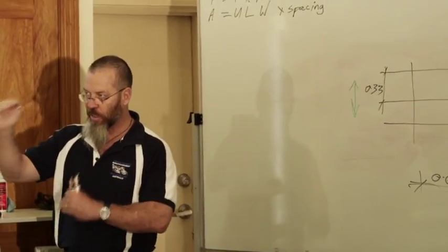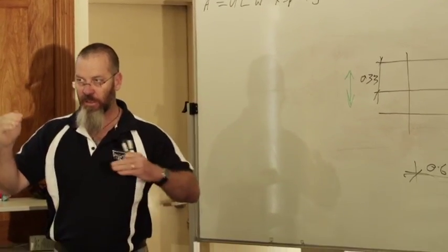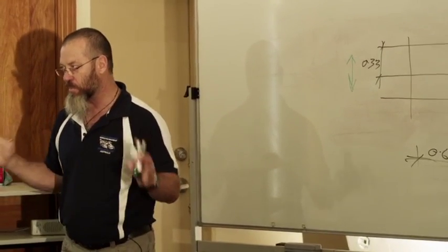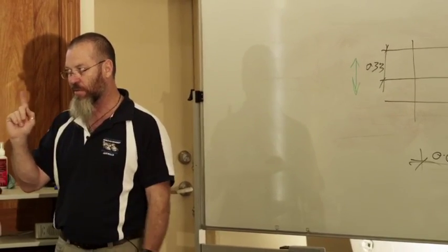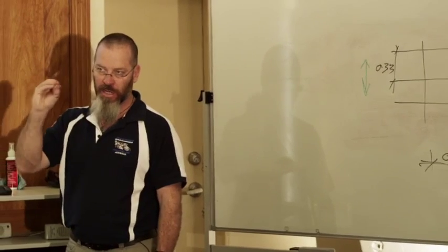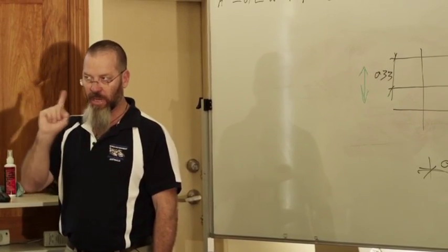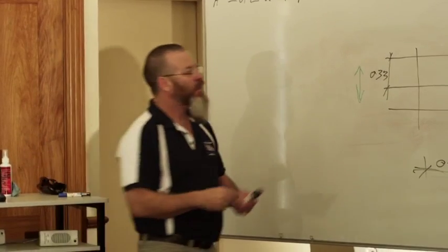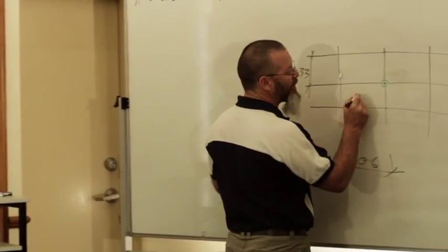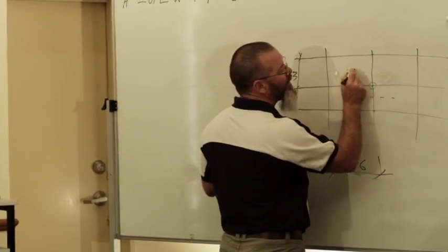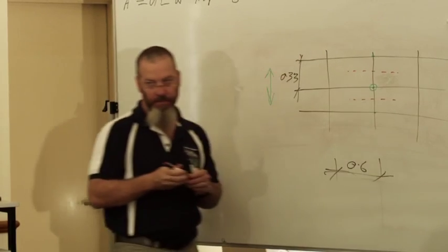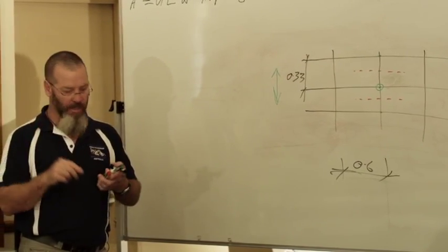I don't want you to think about the distance between your batten spacings or the distance between your rafters, and that'll become evident later on. I want you to think about where your connections are. Think about connections all the time. So it's half the distance between connections plus half the distance between connections. Okay, that's the first thing.